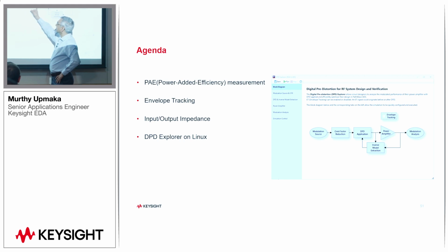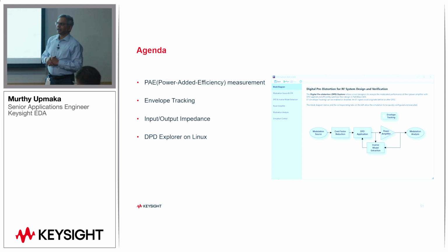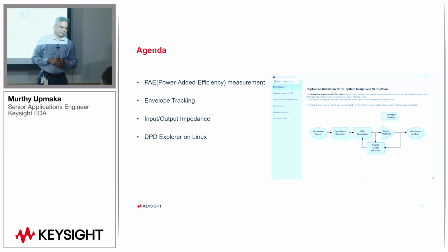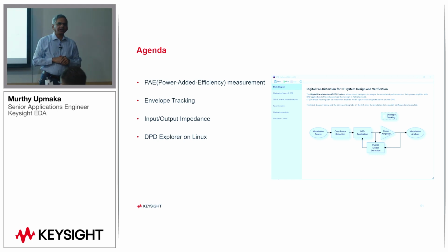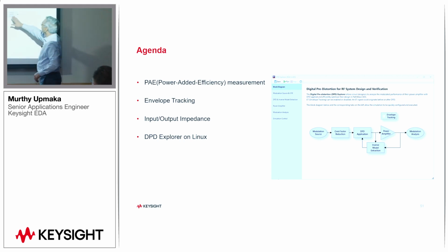It will let you decide. If you click on each one of these blocks, it will open up a next UI, and then it will let you set up what kind of waveform you want to put through your amplifier, right? And then sometimes, this is something that system level people do, that they massage the waveform to reduce the peak to average. The lower the peak to average, the better for the amplifier and even better for the DPD algorithms to linearize the amplifier.